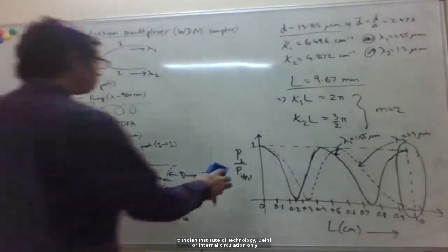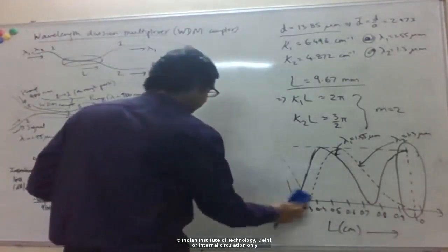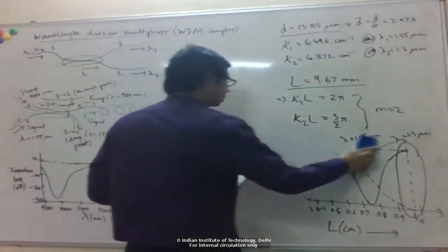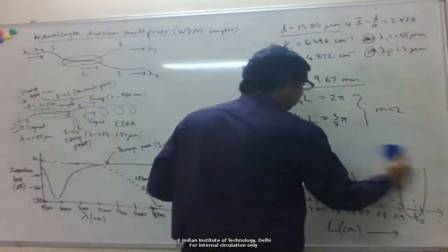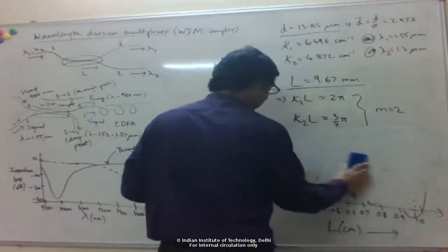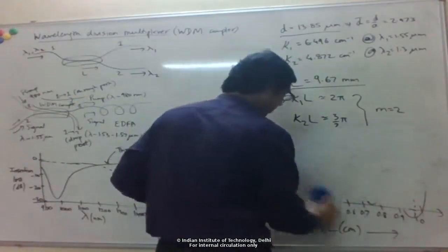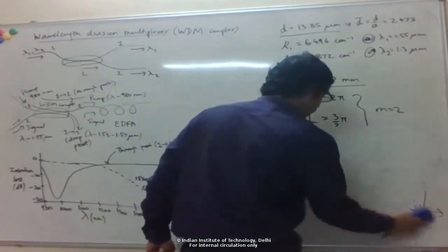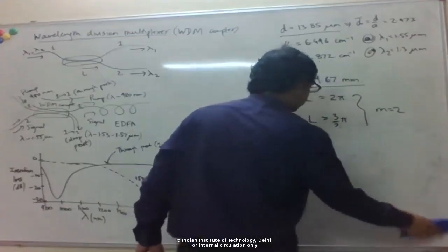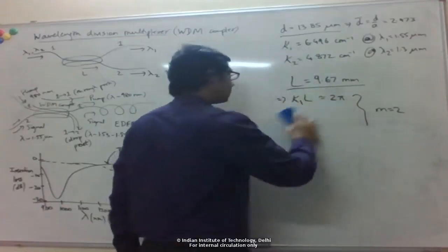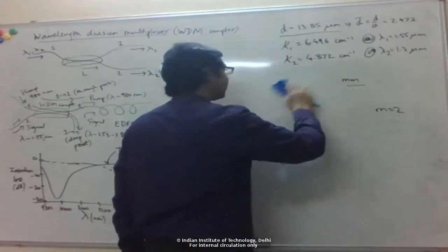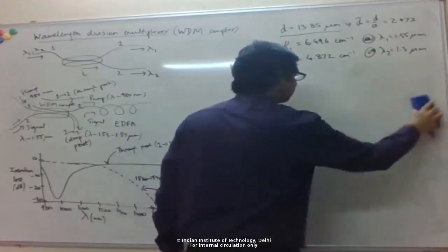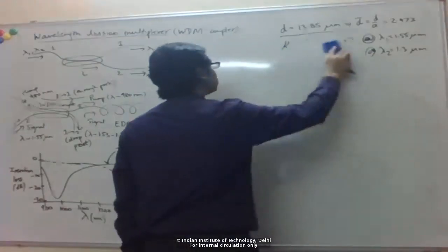Okay, so next topic of discussion is fiber polarization controllers. So we had briefly discussed how polarization evolves in single mode fibers, right? Because of non-uniformities and stresses, etc., the polarization is actually not maintained, and gets scrambled while propagating through the fiber.